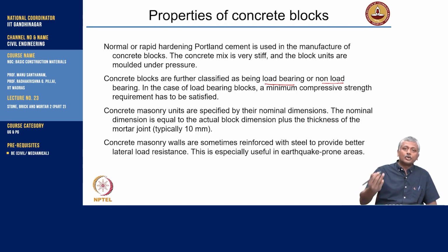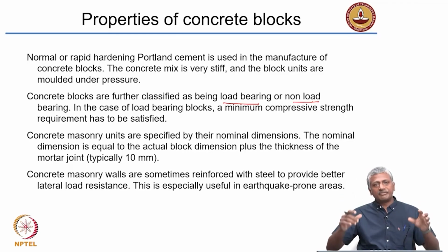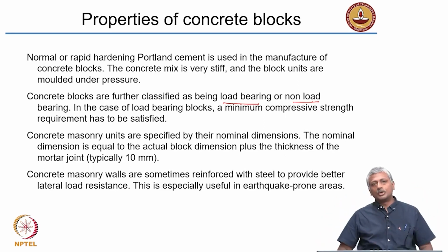Now, in case of a non-load bearing masonry, where do you find that? In most of our modern structures, you have frames of reinforced concrete and the walls are basically filled in afterwards. And the filled in walls do not really take up the load of the structure. They have to only support their own self weight. Those are called non-load bearing walls. In such cases, you can use lightweight concrete blocks. They speed up construction like anything and also improve the insulating properties of the wall.